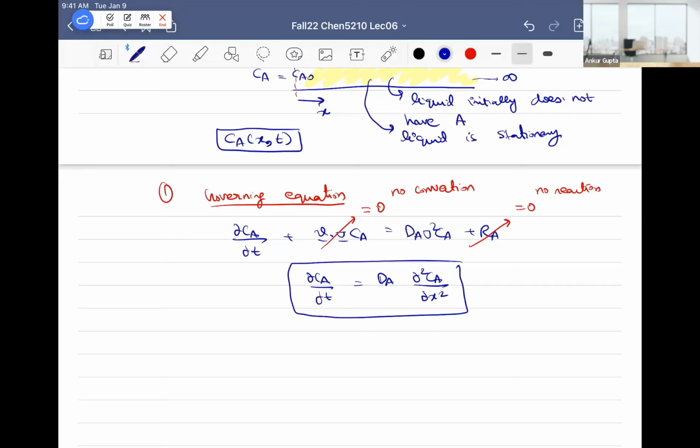The difference is, remember, this is a pseudo binary system. So we only think about those kinds of velocities, mass average, molar average velocities, when trying to calculate them if I have a gas phase system. If I have a liquid phase system, whatever is the velocity of the liquid phase will be the velocity of the entire system. Okay? So a pseudo binary system makes life easier, because the velocity of the solvent will be the velocity of it. That's why it's much easier.